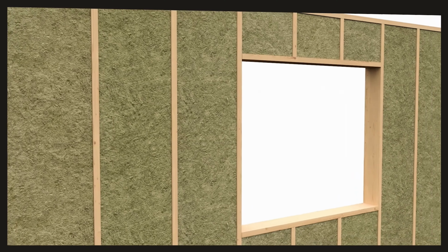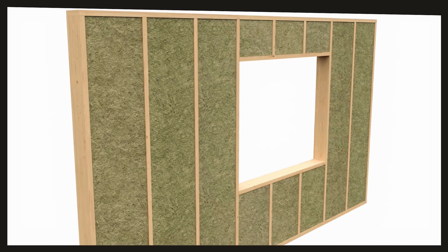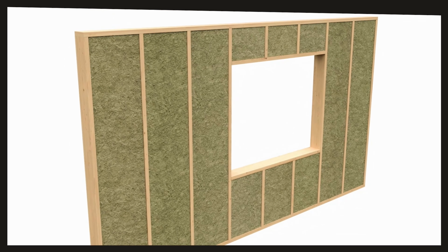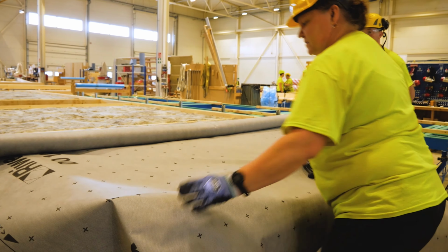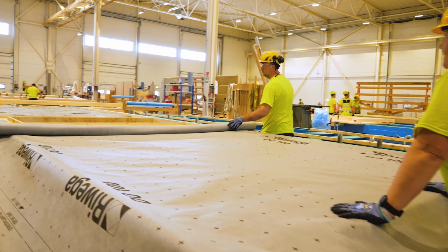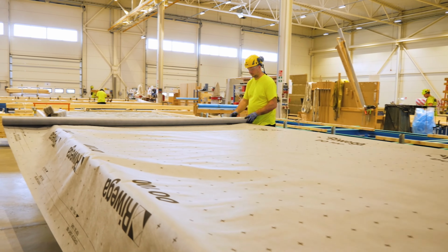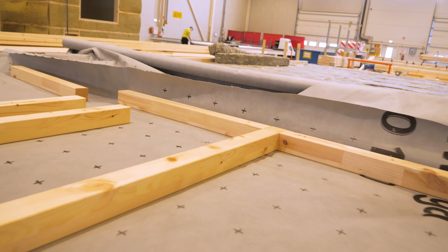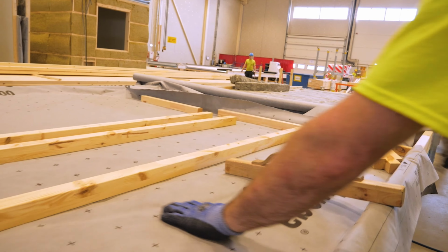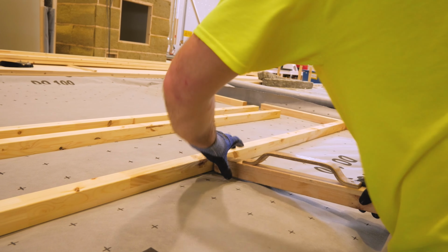To protect the insulation from the penetration of outdoor air, a wind barrier must be installed. Wind barriers are typically made of mineral wool, wood-based materials, gypsum board, or synthetic fabric. Wind barriers are durable, weather-resistant, and designed to withstand wind and moisture loads. The wind barrier is installed on the exterior wall element, over the insulation, and under the exterior cladding battens. It is securely fastened to the frame. The wind barrier prevents the movement of outdoor air and moisture into the construction and, if necessary, allows any moisture from inside the wall to escape.